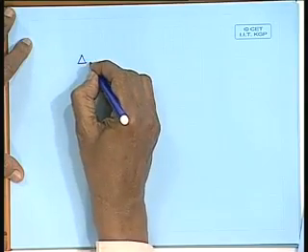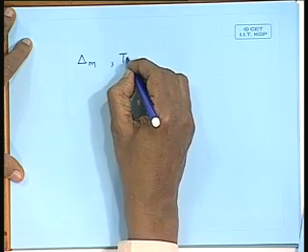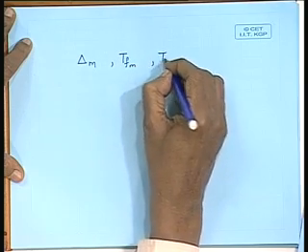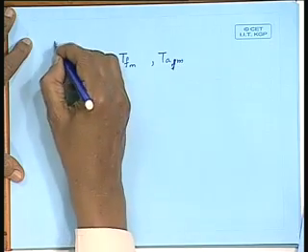How do you prepare the model for the experiment? We have manufactured the model, we know the light weight of the model, and we know what the displacement should be. With this we know the draft forward of the model and the draft aft of the model. These are the known quantities.